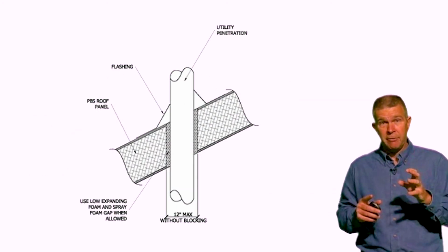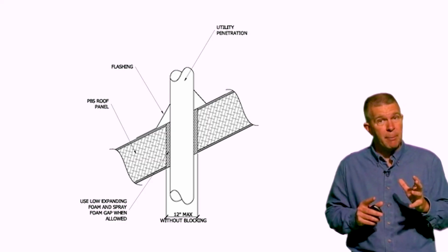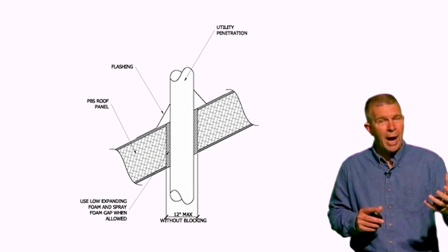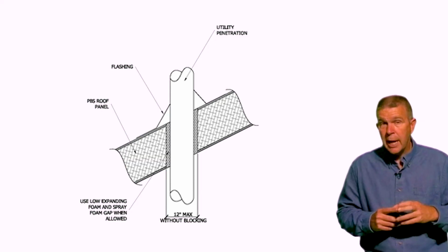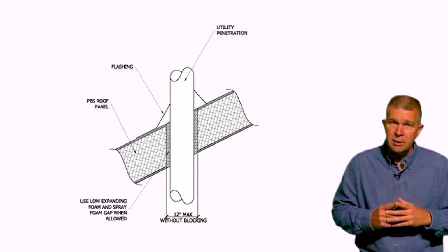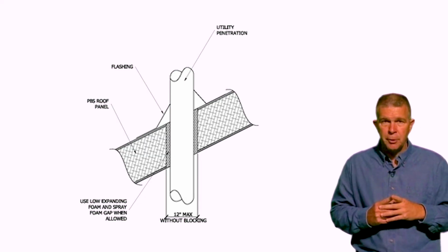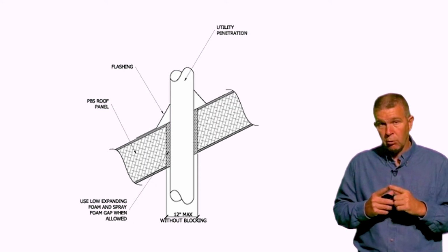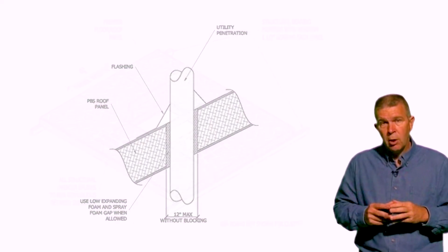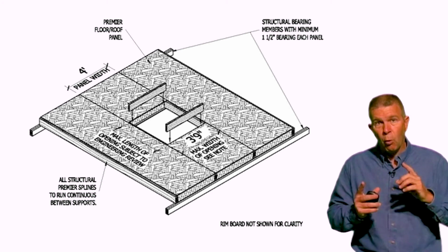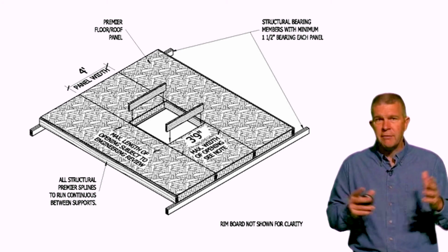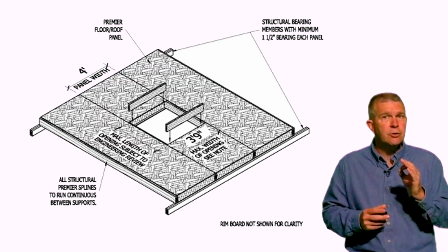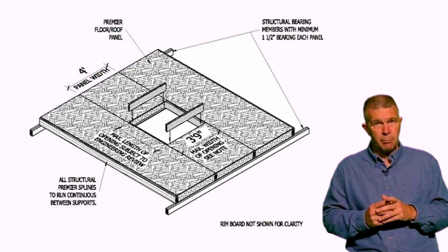From a design perspective, you need to control where these penetrations happen. If you're dealing with things like plumbers who want to put vents through the roof, let's think about how we can combine them to have the fewest possible, and where we are going to put them through the roof. One of the tidbits that I like to point out to builders is, wherever you're going to have penetrations through your roof, because in the future you may opt to add some type of solar system or panel, it makes good sense to make your penetrations always on the north side of your structure. Leave that south side open. It makes future changes to the house and the acceptance of an add-on solar system so much easier when you're not having to go in and start moving things like plumbing vent stacks.